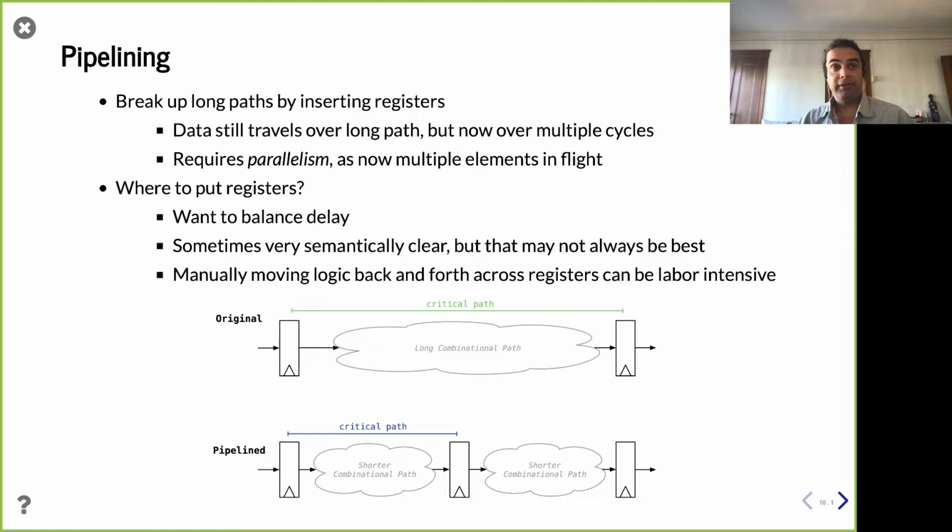You're saying all that, right? Using high level synthesis, or HLS, you're just giving a functional specification and letting the tools figure out the timing specification. And so I would argue this is definitely the direction we want to be heading. I don't know if HLS is quite the right exact solution, but specifying timing in exact detail is a huge source of sunk design effort that I'm not sure humans do better than tools sometimes, right? And so right now, with classic RTL, like Verilog, VHDL, or Chisel, we're specifying the timing very concretely. There's some really interesting research in future languages, things like TL-Verilog, or here at Santa Cruz, our colleague Professor Jose Renau's PyRope, that have different timing semantics to try and let the tools do more of that in a more interesting way.